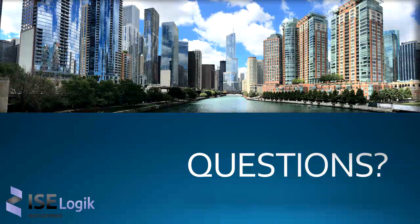Now here's one that's a little different. Can any of your products be used for a traffic coating? No, actually, that's a great question, but these products are for moisture mitigation, and so any of our topical products would not be for the traffic coating. There would need to be a floor covering system or a traffic coating applied directly over it, because these are not standalone moisture mitigation and traffic coating products. They're just moisture mitigation and adhesive products.